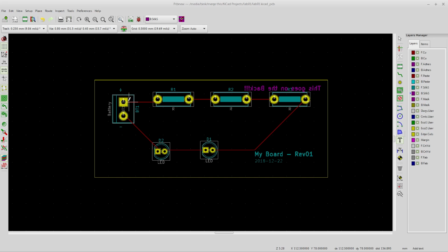So if your pin is a tenth of an inch, you maybe want to go 0.11, 0.12 with the hole size. Remember, the solder can accommodate pretty easily for most things, but not too big, because you don't want a big flood of solder flowing through, making a giant mess.